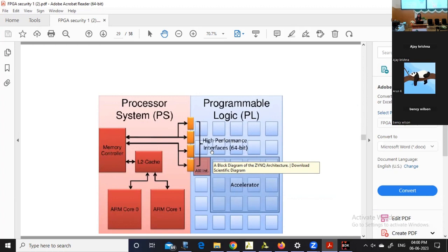And logic locking eliminates almost all attacks. Reverse engineering, not possible if we do logic locking without the proper key. Okay. Then side channel attack. After logic locking, if we analyze the side power and all, additional gates we have already placed. So an attacker may not be able to know the correct thing. Then insertion of Trojan.